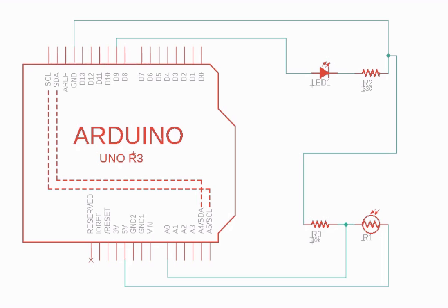So this point would come very close to reading 5 volts, or the top of its little scale. And as it gets darker and darker, this resistor will increase and increase, and the voltage measured between the two will decrease.